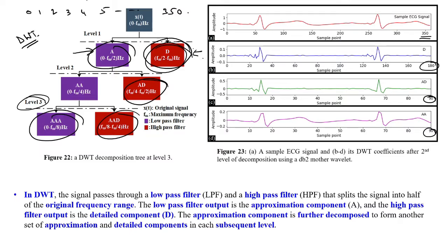However, when you are doing this, you will eliminate all the odd samples or the even samples, depending upon you, and the new time domain will again be 0, 1, 2 and so on. By doing this, your 350 becomes 350 divided by 2, that's 175. So you'll get 175 samples in both the signal components.